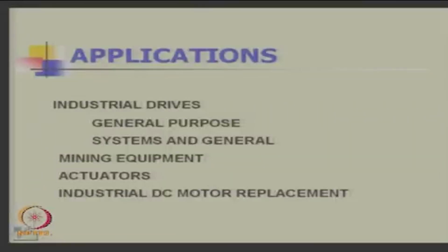And applications where they have found switched reluctance motors useful are industrial drives, general purpose systems, then mining equipment, actuators, and industrial DC motor replacement. Whenever they have DC motors gone bad, they have tried to replace them with SRM as variable speed drives, which we call retrofitting.